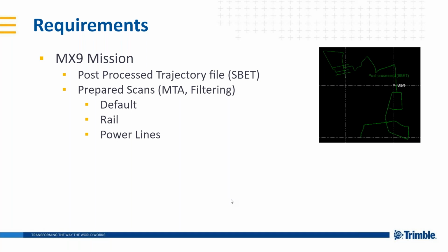By prepare, I mean some pre-processing has to be applied to our raw data from the laser scanning. The first one that we are familiar with is the multi-time-around correction. We also use the SBET file to georeference our raw data into real world coordinates.